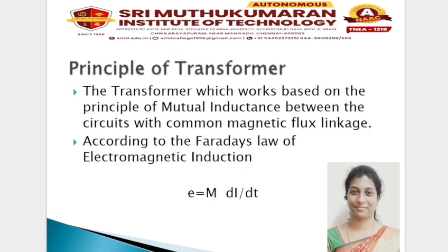The next one is the principle of transformer. What is the principle of transformer working? The transformer works based on mutual inductance, when two coils influence each other magnetically. According to Faraday's law, EMF is induced whenever there is a rate of change of magnetic flux. If there is any rate of change of magnetic flux, at that time the EMF is induced according to Faraday's law. This principle allows energy transfer without mechanical motion.